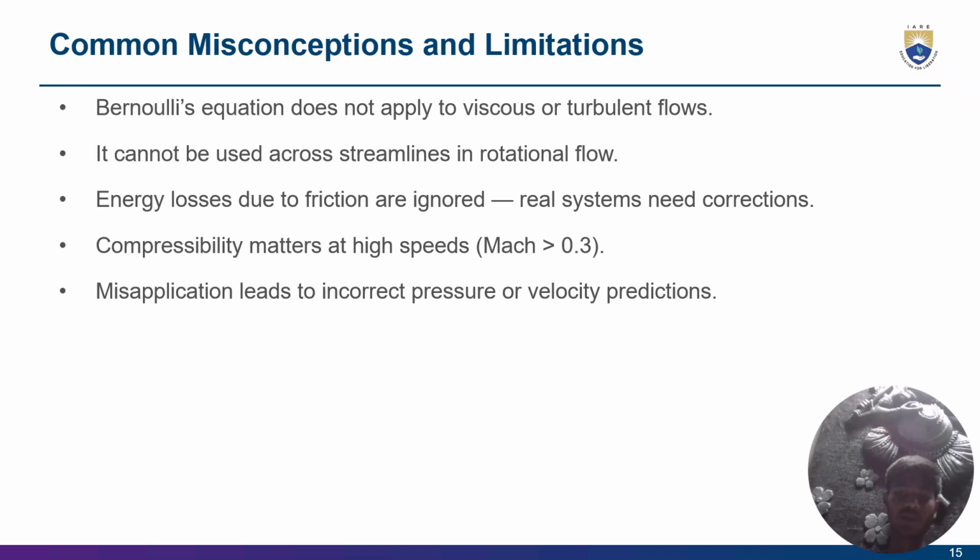Common misconceptions and limitations. Bernoulli's equation does not apply to viscous or turbulent flows. It cannot be used across streamlines in rotational flow. Energy losses due to friction are ignored. Real systems need corrections. Compressibility matters at high speeds.